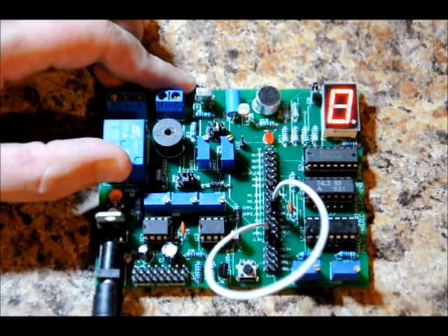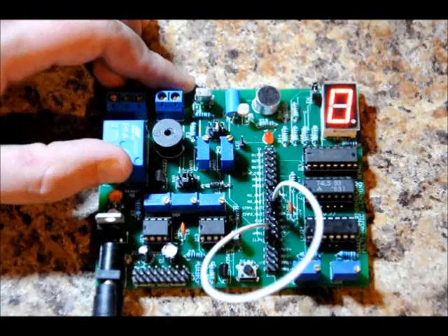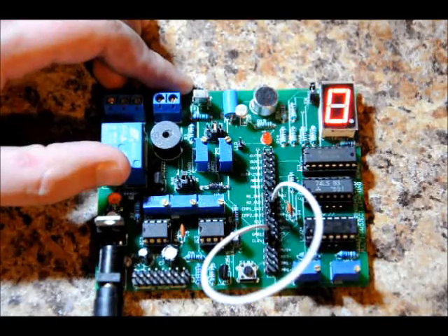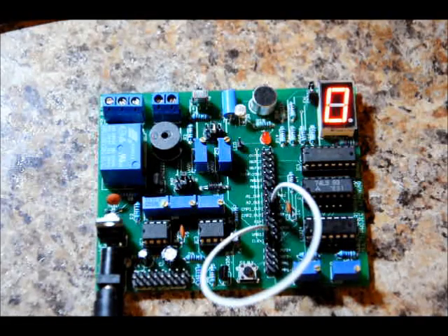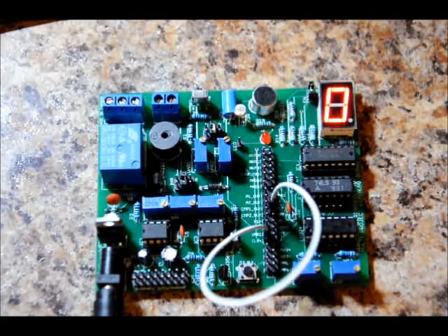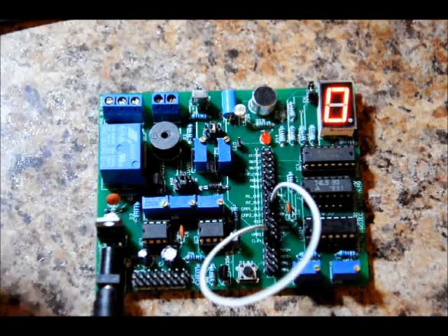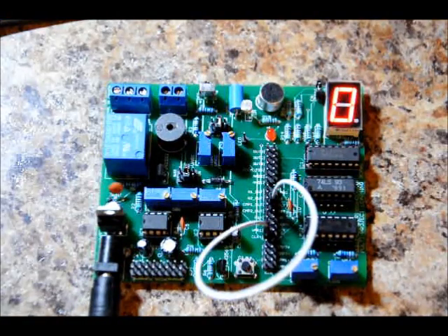Now, you might be wondering, why isn't it counting yet? Do you remember those AND pins, AND1 and AND2? Right now, those are left floating, and they're located right here. Now, what's floating, you ask? I'm glad you asked. Floating is when you don't have it connected to a signal line or 5 volts or ground. It's just left connected to nothing. And when it's left connected to nothing, the 74LS93 thinks, okay, they're both at 5 volts, so it's in constant reset mode. So we have to make our connection.